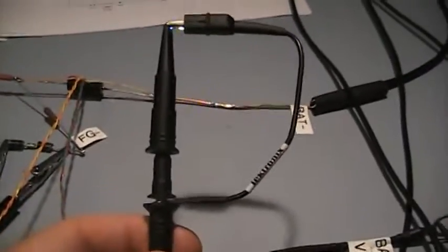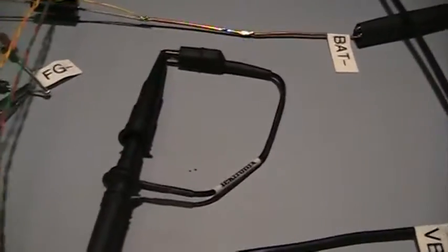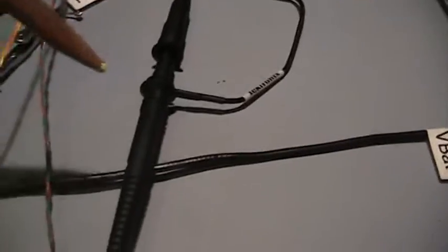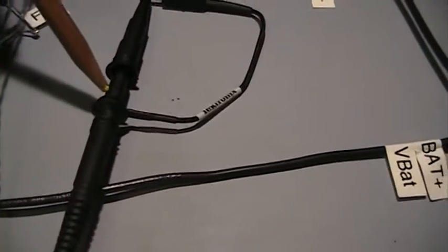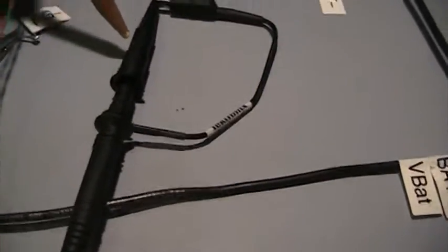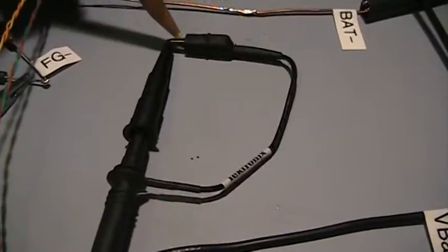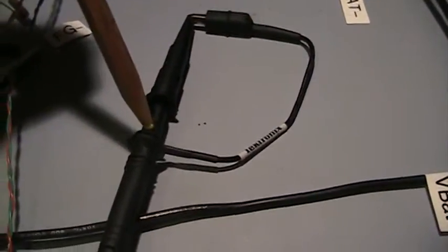Now, to further illustrate this potential problem, I am just looping the CSR probe here onto itself, so it's just forming a simple loop. The coax comes through here. The ground does carry on at least to this point, but the center conductor goes all the way through to the tip, and then our ground lead comes all the way back this way.